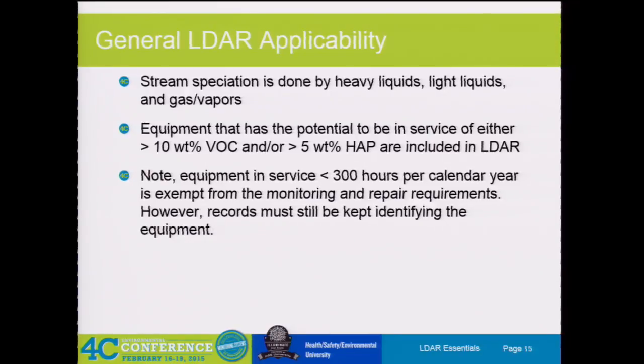So it's always a living or evergreen procedure. You re-highlight that one drawing, you update your LDAR program, and you put that new piece into your P&ID binder, basically. It's very time consuming, but with the complexity of these types of programs, you might have 30, 40,000 different components in the system or even more. If I'm investing this much time, I want to have the most up-to-date records and the best possibility of not getting in trouble.